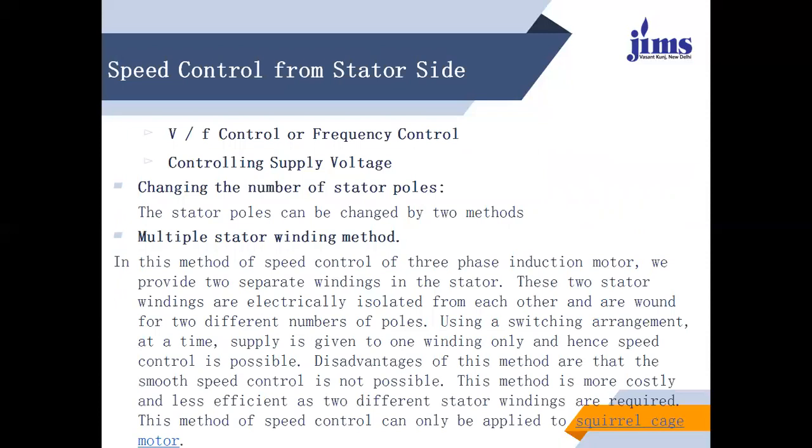Initially, we are looking at the V by f control, which will be performed on the stator side by V by f control or frequency control, or controlling the supply voltages. Changing the number of stator poles is another method. Stator poles can be changed by two methods.